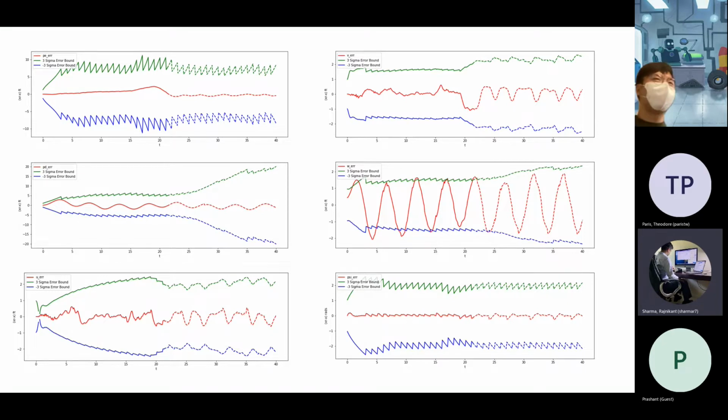In order to mark the moment of touchdown, we have created a flag for when the PD error is below a certain number. We consider the quadcopter to have touched down, and then we overwrite the states of the quadcopter to follow those of the ship.